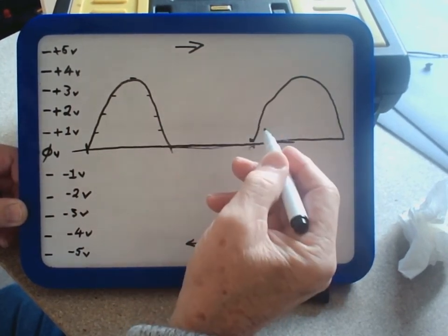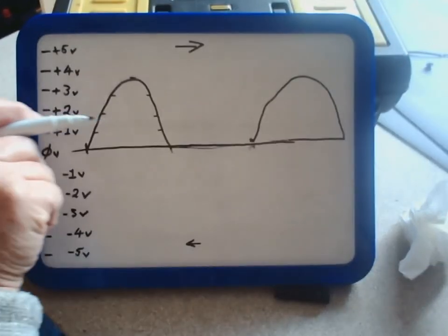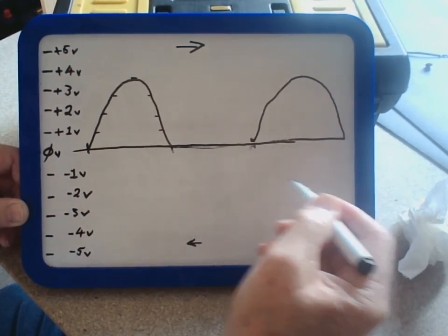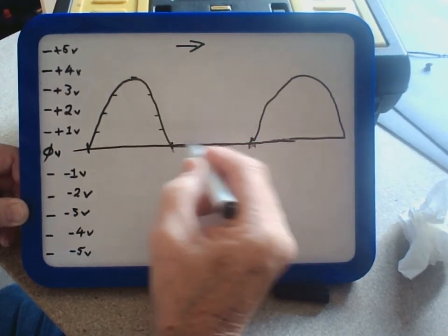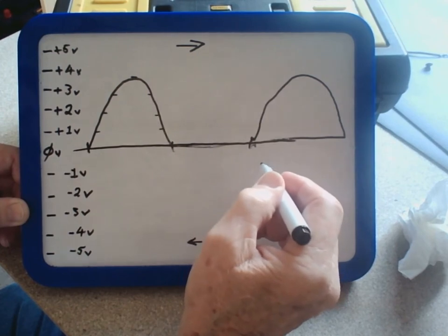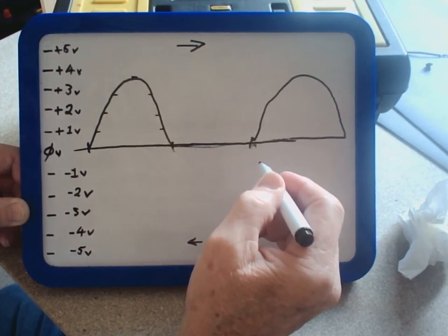But what this means is that although we have direct current, with electricity travelling in one direction, it's not there all the time. From this period here to this period here, there's no electricity flowing at all. And that's why the multimeter showed such a low voltage, because multimeters work on averages of how much voltage there is in a circuit every second.